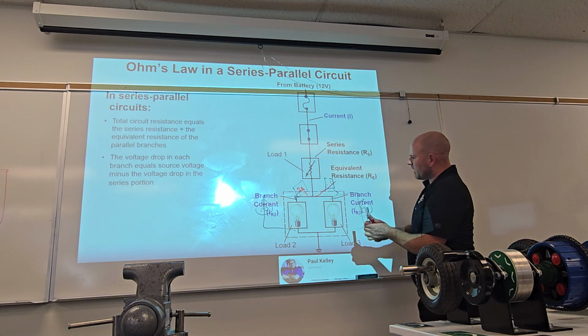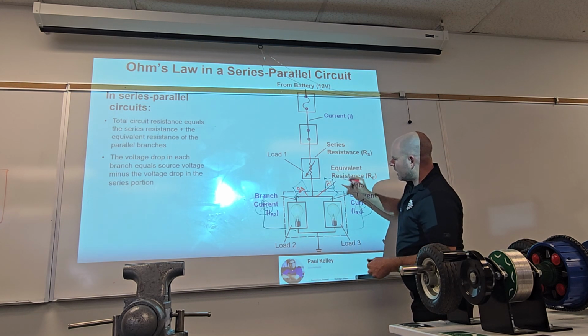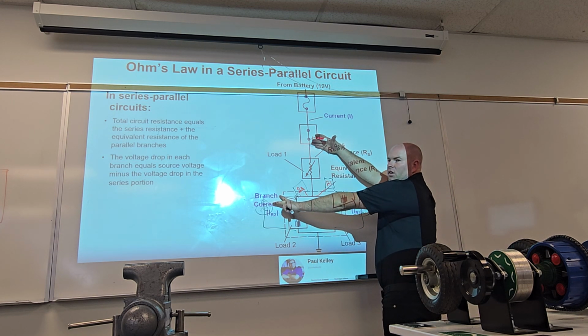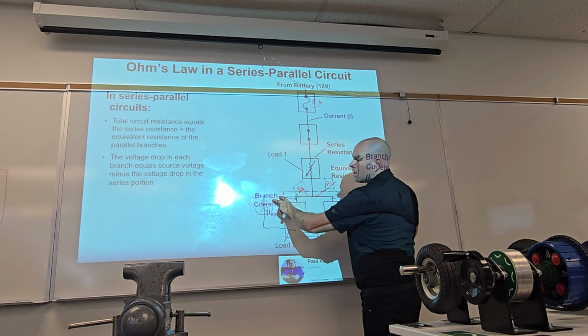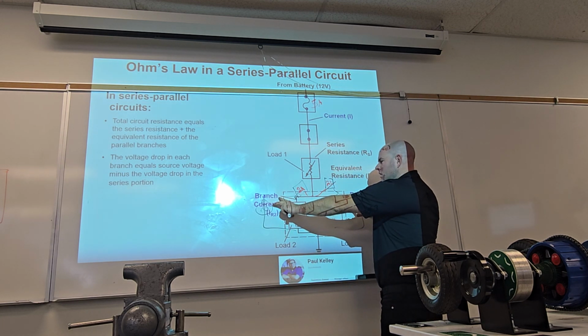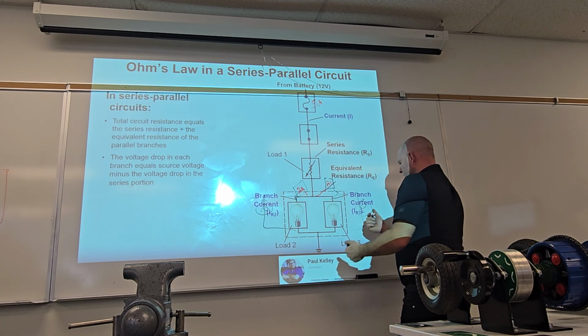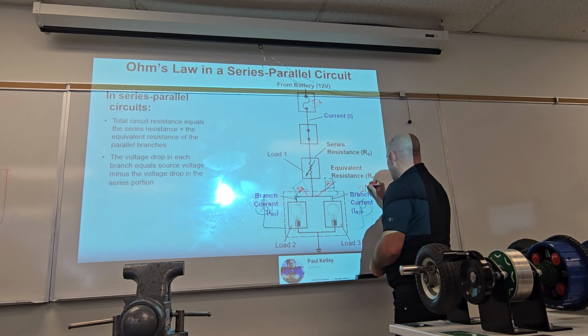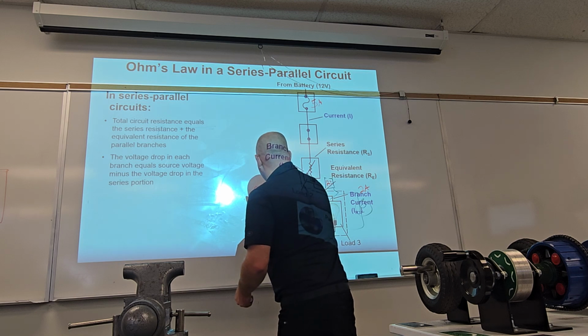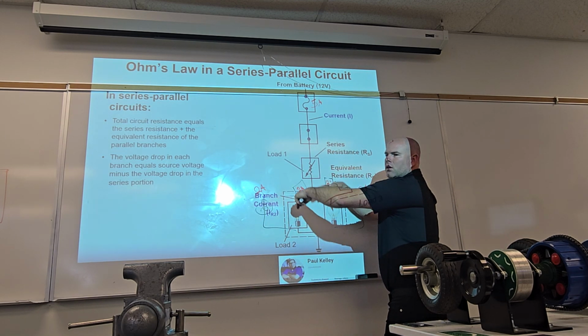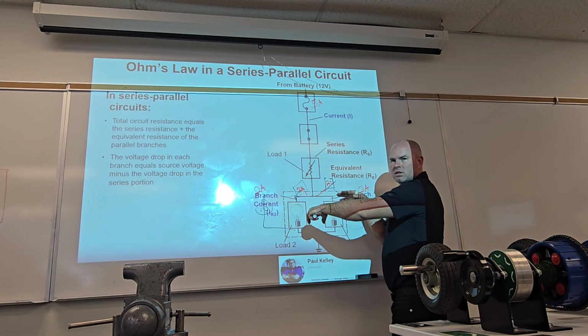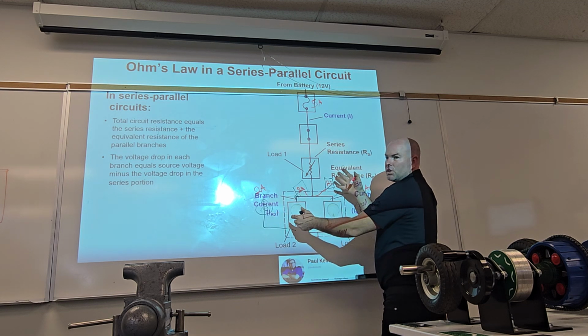If I had 2 amps and 2 amps and no extra lights, how much did I have here? Let's say this is a 5 amp fuse. 4 amps, okay, right? It's getting close. I think it's okay. Then the truck driver adds this bulb and this bulb, and now you have 2 more amps and 2 more amps. Do you understand? If you're adding loads in parallel, that's going to reduce the resistance. That's also going to increase your amperage, right?